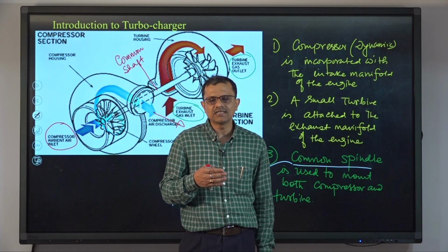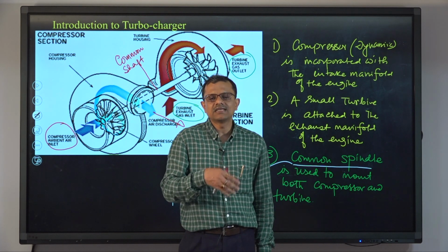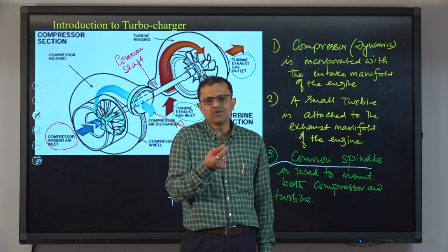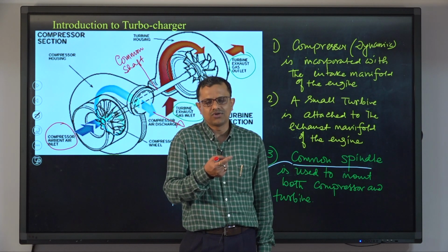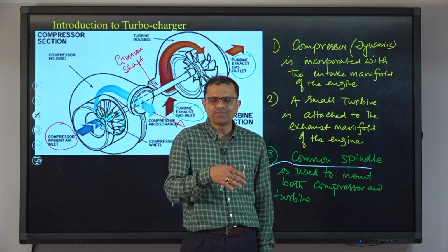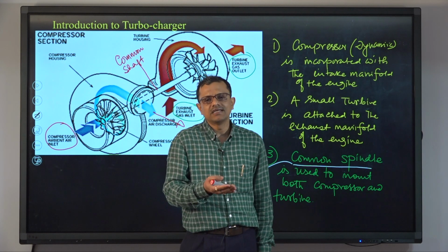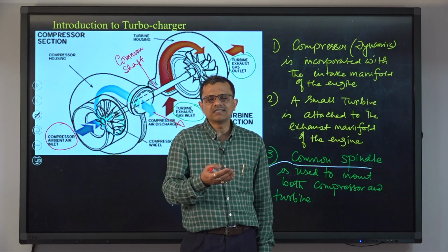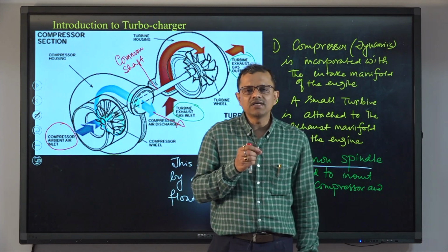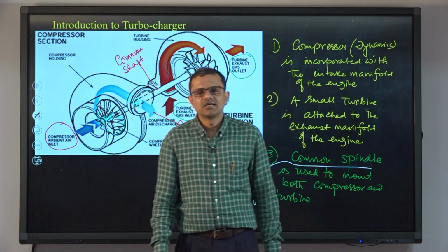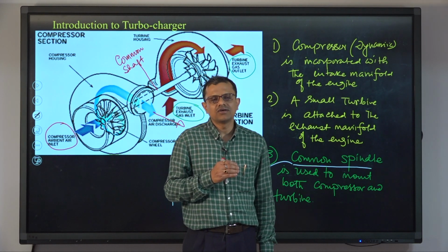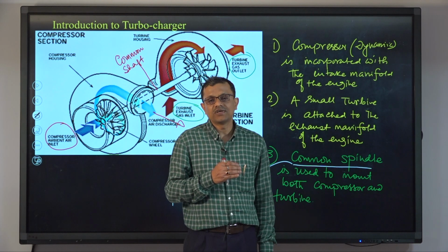So, the rise in temperature, if it is beyond a certain limit, essentially that in the intake manifold, again the consumed air should be compressed during the compression stroke. So, an increase in temperature associated with the increase in pressure inside the compressor will be further enhanced inside this engine cylinder, and that increase in temperature will eventually invite one important or rather detrimental problem which is knock. That is, knock is really a severe detrimental problem for the SI engines.